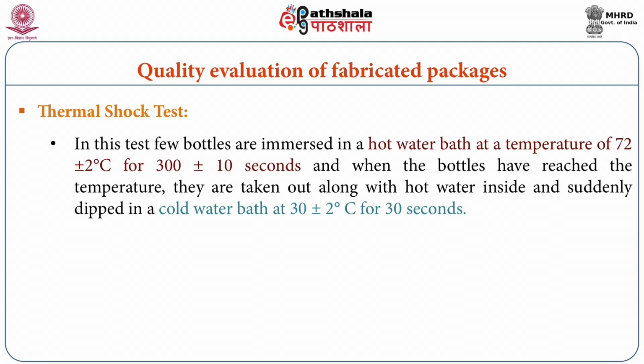for 300 plus or minus 10 seconds, and when the bottles have reached the temperature, they are taken out along with hot water inside and suddenly dipped into a cold water bath at 30 plus or minus 2 degrees centigrade for 30 seconds, and then the cracks developed are observed.